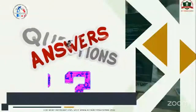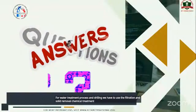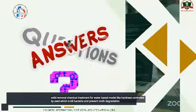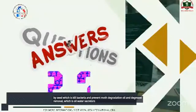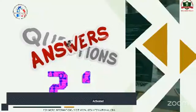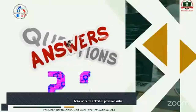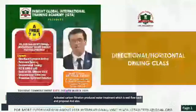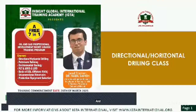For the water treatment process in drilling, we have to use filtration and solid removal, chemical treatment for water-based mud like hardness control, biocide, which kills bacteria and prevents mud degradation, oil and debris removal, which is oil-water separators, activated carbon filtration, produced water treatment, which is well flow, pack, and disposal. And also there is water management at drilling sites, which is for recycling, reduction, and re-injection into the reservoir. That's it.